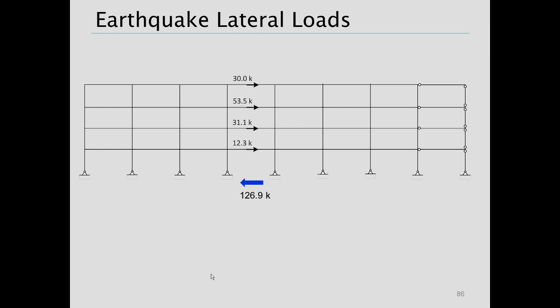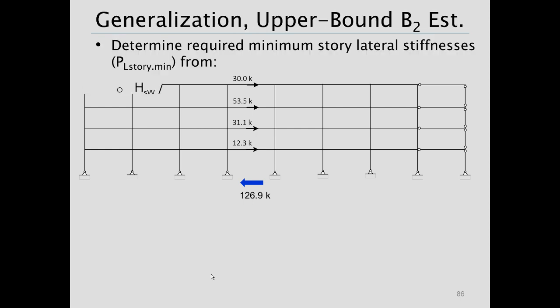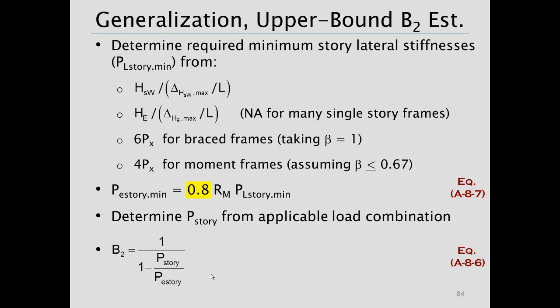the question is, why are we not applying the notional load of 0.002 Y? Okay, very good question. The reason for that, if you go back to look at what we talked about with the rules for the direct analysis method, basically if it is a stability non-critical frame, then you are not required to include the notional lateral load with a lateral load combination.